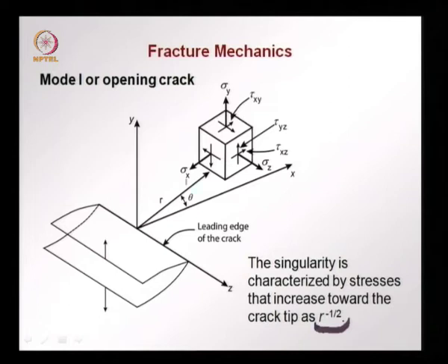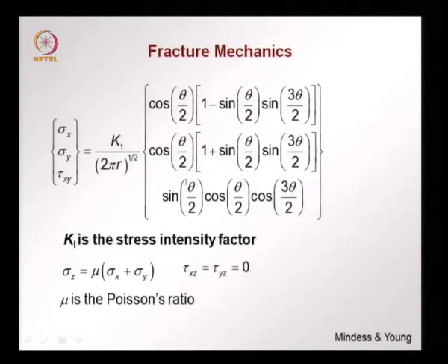That is why it is called a singular stress field, and the equations for this are given here, where we have sigma x, sigma y and tau xy, the stresses ahead of the crack tip. The point that we are discussing is defined in terms of r being the distance from the crack tip to that point, theta being the angle from the crack plane.